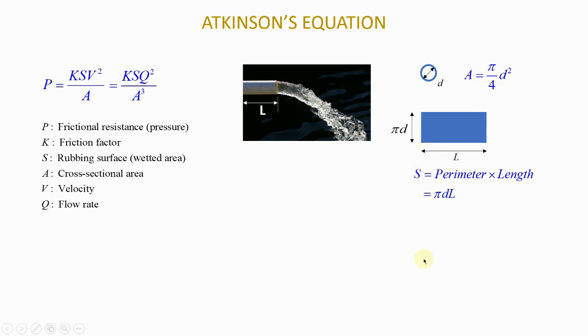Very, very important. And lastly, before we move on to examples, I want to speak of the air power. The air power is given simply by rho multiplied by g multiplied by q and multiplied by h. Rho is the density, g is the acceleration of gravity, q is the flow rate, and h in this equation, when we're dealing with a ventilation system, is the water gauge. So that's how we will refer to it. H is the water gauge. Very, very important. So that's how you will get the air power if ever you had a question like that.